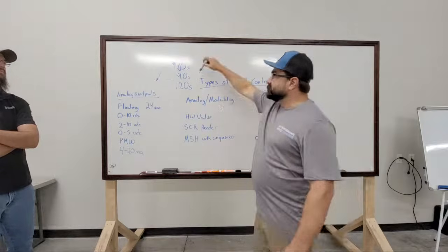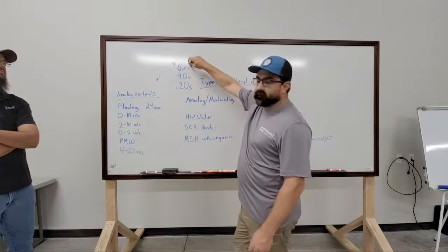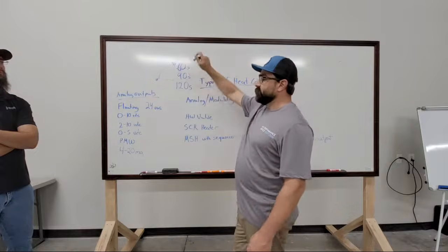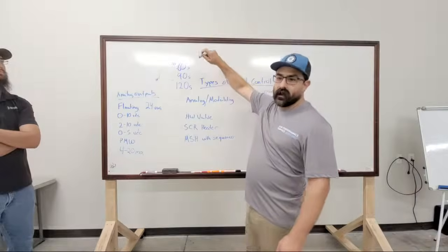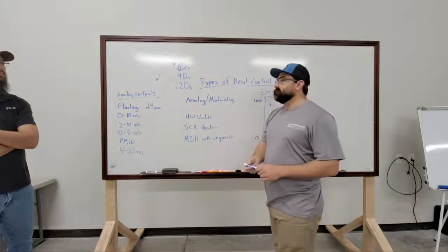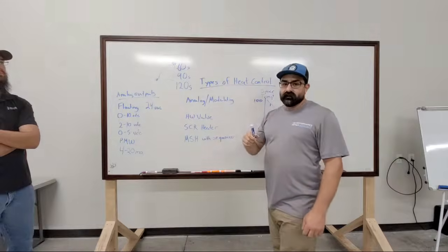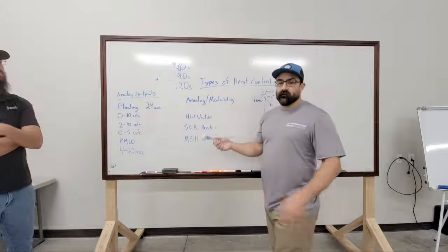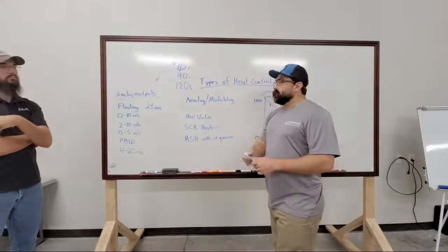So if you have a 60-second actuator and you want to open it to 50%, I would send 24 volts to that actuator for 30 seconds. In theory, it will open to 50%, or 45 degrees. And if you want to close it, you send 24 volts to the closed side for 30 seconds and it will go back the other direction.